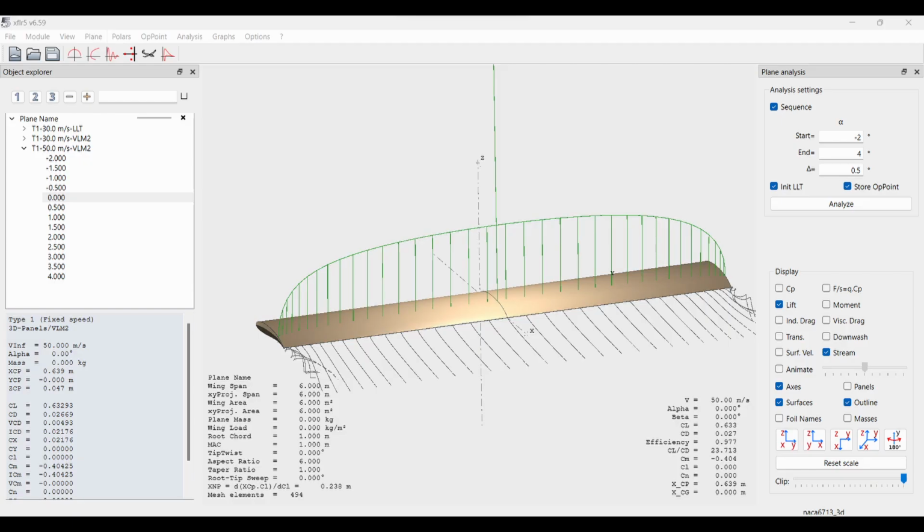What I wanted to show here now is results of a different software that I also used. It's XFLR5. This is the same wing setup as in ANSYS. The difference here is that I removed the symmetry condition and now made the wing 6 meters long, so we have 2 tips. XFLR5 is made mostly for inviscid simulations, meaning effects like separation and friction are not looked at. There are some formulas for estimating them, but definitely not as accurate as the other simulation.